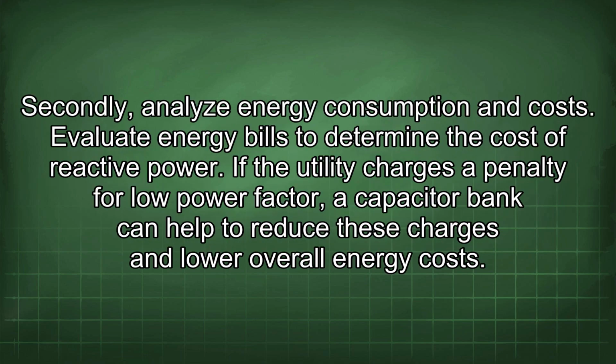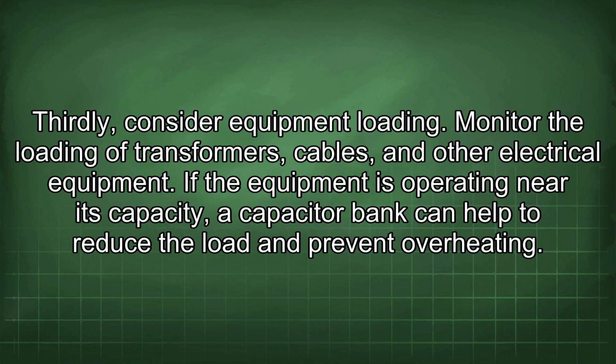Secondly, analyze energy consumption and costs. Evaluate energy bills to determine the cost of reactive power. If the utility charges a penalty for low power factor, a capacitor bank can help to reduce these charges and lower overall energy costs. Thirdly, consider equipment loading.